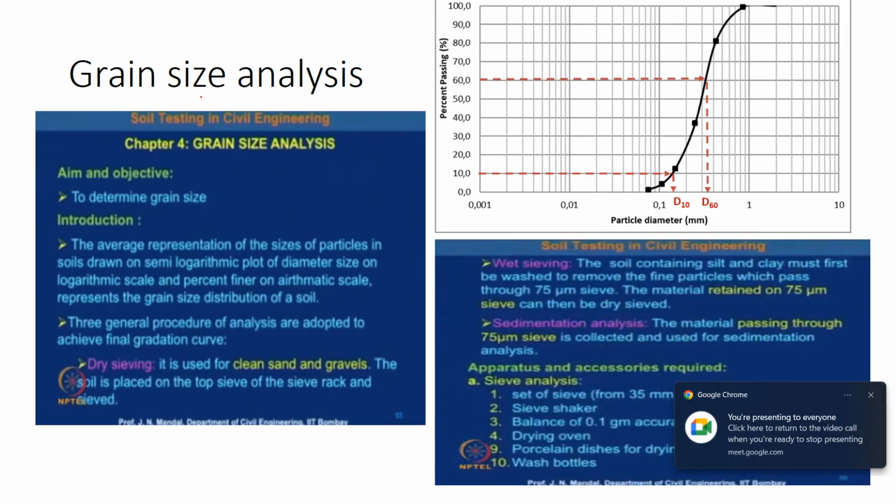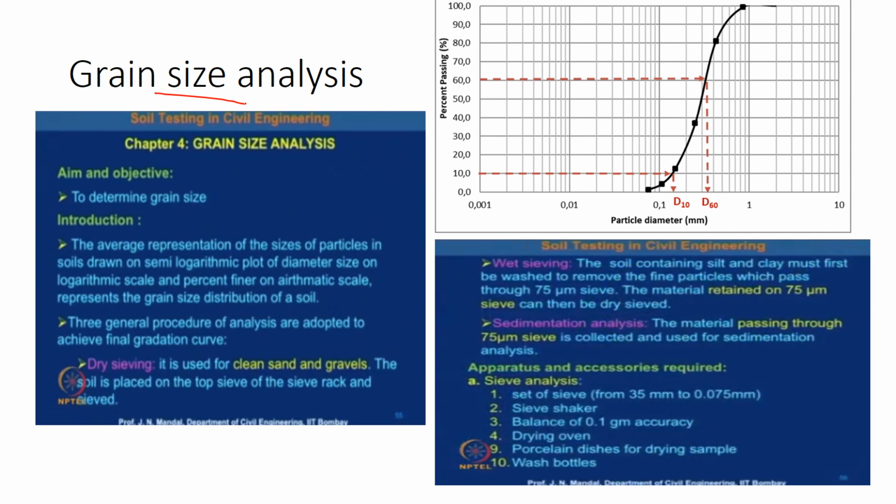So grain size analysis, as I said, is like the internal structure of the soil. It is very important and helpful in the design of filters, even filters in dams. In dams we call them filters, where in your downstream you have to allow water to seep through the filter, or else water pressure will build up, but you should not allow soil to escape. So the filter material itself is a granular or soil material, which will restrict soil but not restrict water.